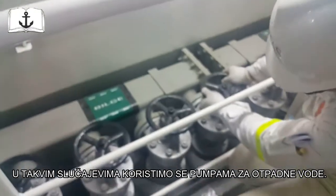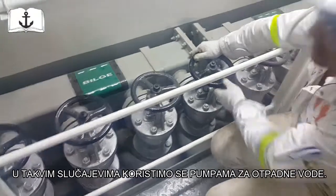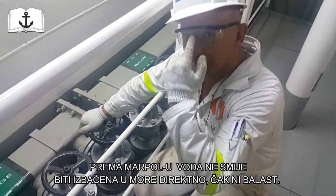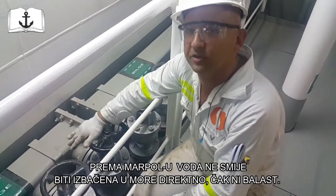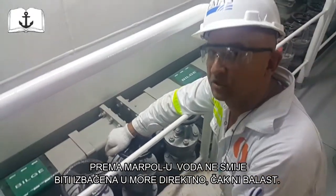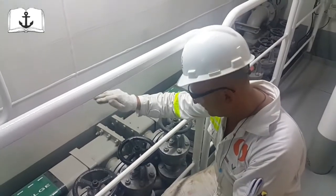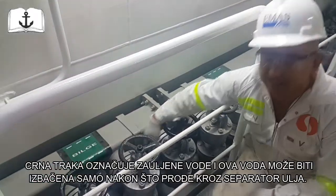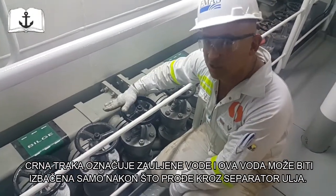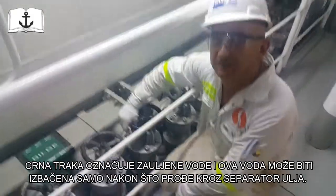You're opening the valve, you're starting up the pump, and this water is going to the bilge tank. We have the regulation now that no water from the ship should go out directly. Even not the ballast water, because it's going to the ballast water treatment system. But this water, you have a black valve and you have a black stripe here. It means it can be contaminated with something. So basically we are pumping this water to the bilge tank, and then we can discharge it the legal way with the oily water separator.